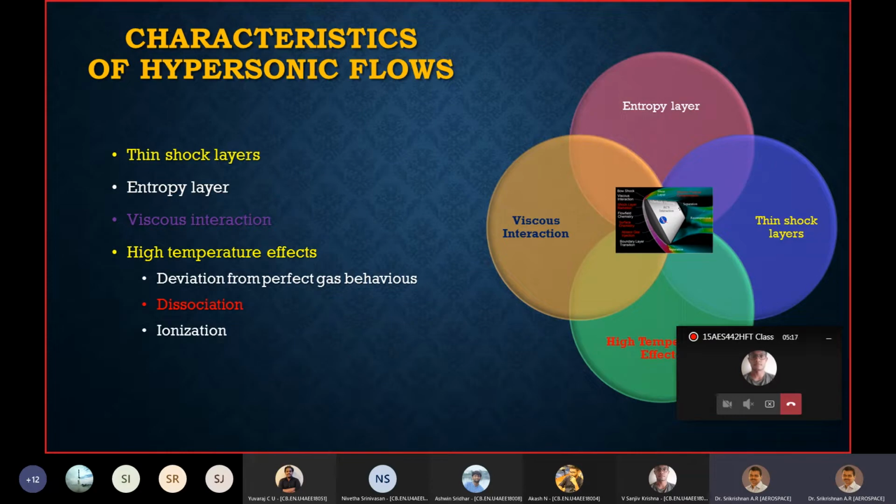That is because of hypersonic flow applications in space propulsion systems. So only beyond the atmosphere, where the density becomes gradually lower and lower, the rarefaction effects become important. Since in such situations you have hypersonic vehicles as well as rarefied gas, you have to consider the combination of the two. But otherwise, in hypersonic flow, rarefaction cannot be considered an inherent part of it. It happens only when you go beyond the atmosphere. So that's the reason why I limit our attention to these four, which can happen anywhere.